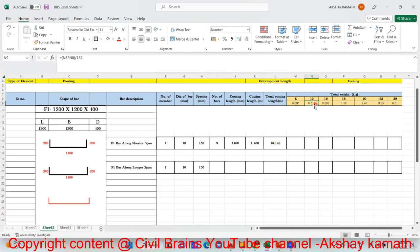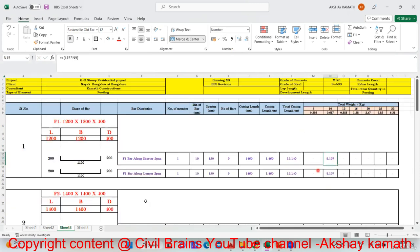It is 0.617. So the weight will be plus, open the bracket. Okay. Total cutting length. If I multiply this cutting length with the weight of a 10 diameter bar, that is 0.617, and then close the bracket, hit the enter button. So 8.11 kg is the total weight of my bar that is required if I want to prepare F1 footing of only one number. So 8.11 I got. Yeah, here also it is 8.107.